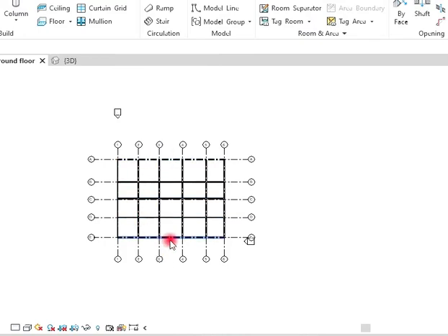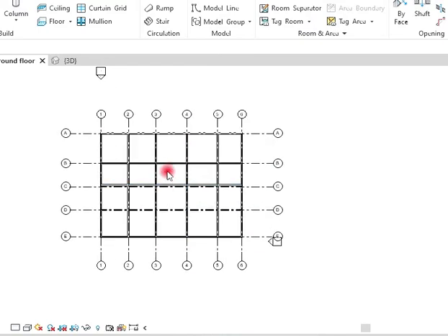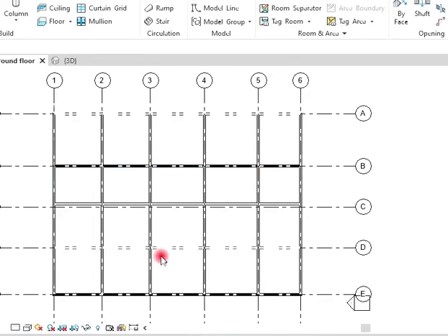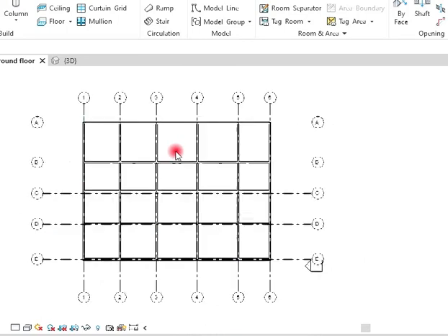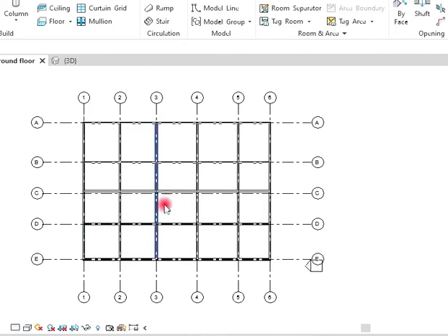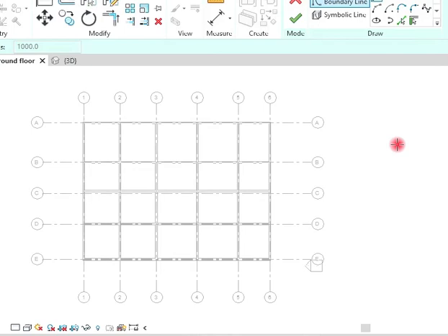Once you insert a floor, it has blocked where you need to put your staircase and thereabout. So what you need to use is a tool called shaft. If you click on this shaft, it will pop up. It's asking you what you need to do.